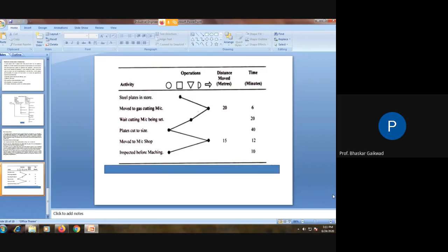Correct. Now, after getting this raw material near the machine, what is the next thing? We have to wait for die setting. Means there is a press machine, there is also a die, but we have to set the die on the machine table, adjust the stroke, and clamp the die. So there is some delay. Once the raw material comes to the machine and we start to set the die on the machine, there is a delay. This point will come under the D.